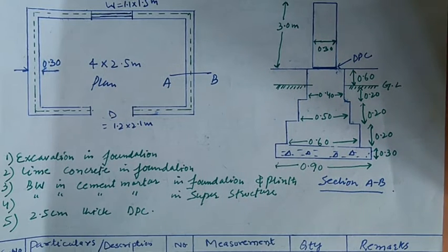As of now we have a simple room which does not have any cross wall or junctions with the main wall, therefore the length in this question will remain the same. Later on, when we switch to difficult questions, a two room building with veranda, there we will see how the length will change in the center line method.